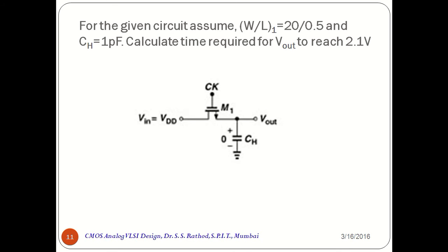Thus, the MOS devices operating in deep triode region are sometimes also called zero offset switches, to emphasize that they exhibit no DC shift between input and output voltages of the simple sampling circuit.